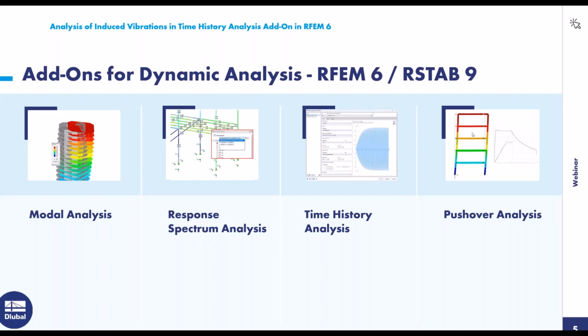I will go now to the right side because that's the pushover analysis. It's more familiar to the response spectrum analysis because here we are able to do a pushover analysis for structures. Therefore we can calculate the capacity curve of the structure, and we are able to do the pushover analysis for such a structure with nonlinear hinges according to FEMA or according to Eurocode if you want. Yes, of course, and then you get the response for that, also in the nonlinear case.